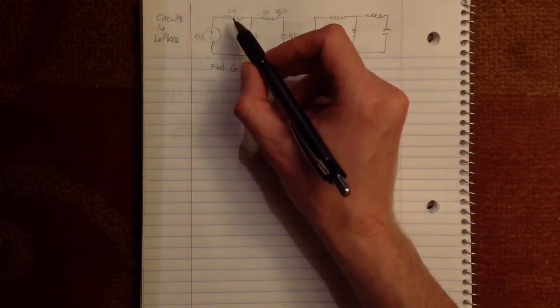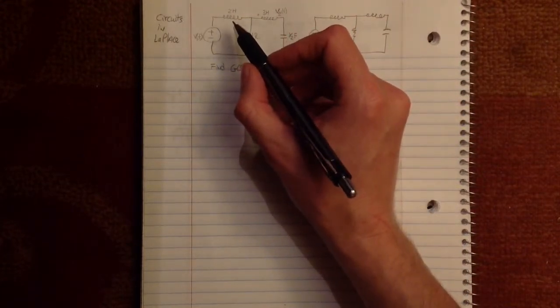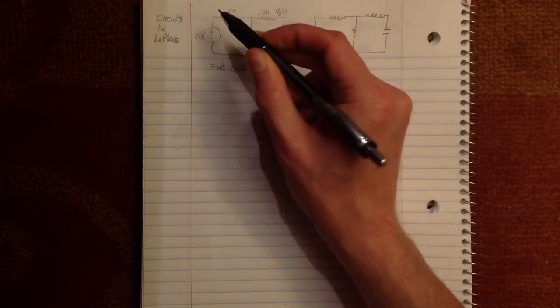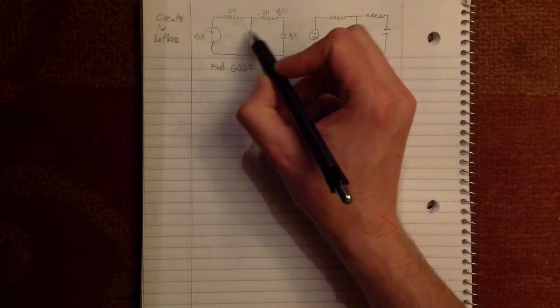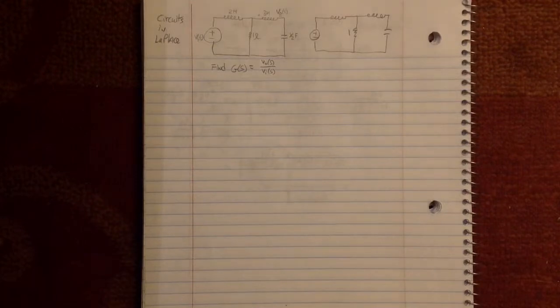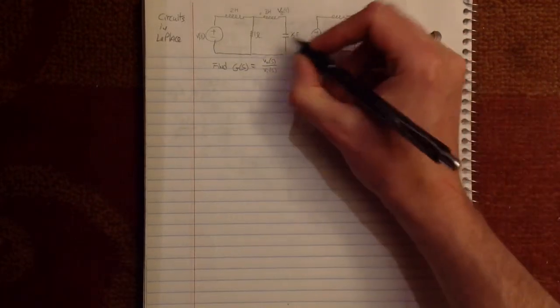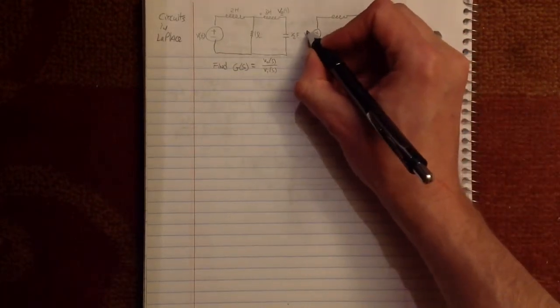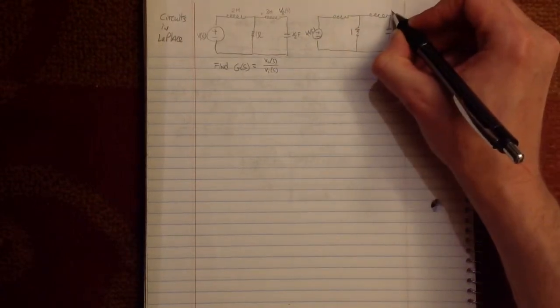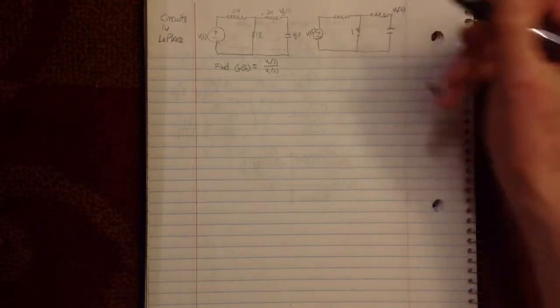So you need to pay specific attention to anything that stores energy. So not resistors. That's just going to be a constant. So just write, it's 1 ohm, 1. It's a constant, that's it. So Vin of t, we're just going to put in the frequency domain, Vi of s. And the voltage out, we're just going to put in Vo of s as well.